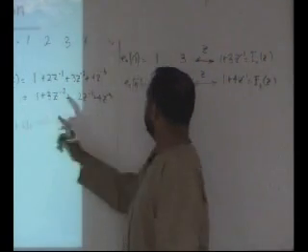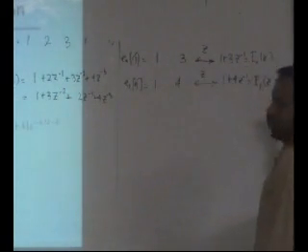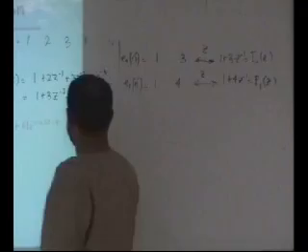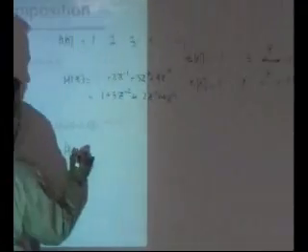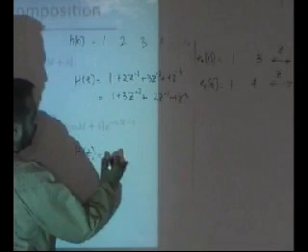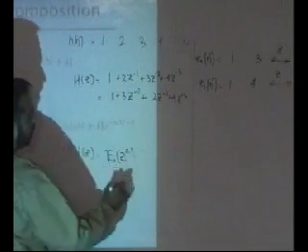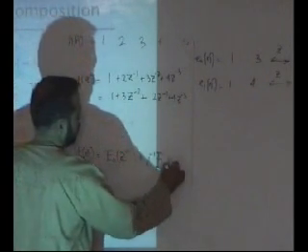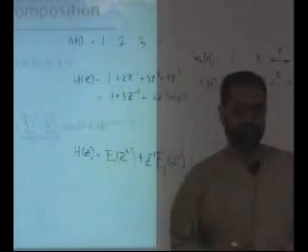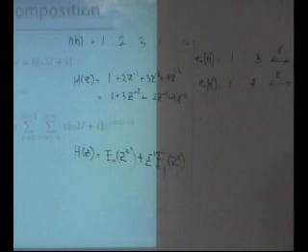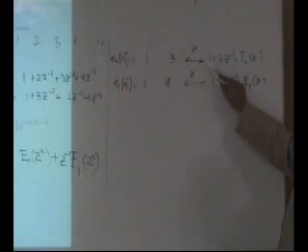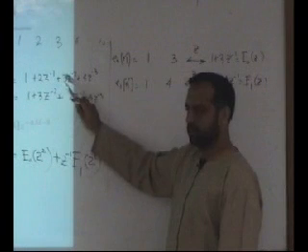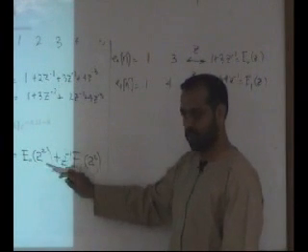I really want to write h of Z in terms of E0 of Z and E1 of Z. Can I do that? Yes. How? Looking at this, I know my h of Z is in fact equal to E0 of Z square plus Z inverse E1 of Z square. And you can check. If you say E0 of Z square, Z will be replaced by Z square. It will be 1 plus 3Z minus 2. So it is E0 of Z square.